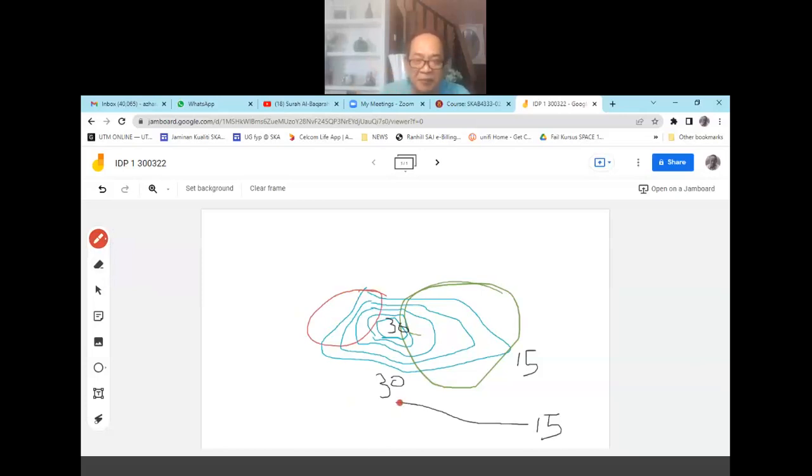are closely spaced together, it indicates that it is quite a steep slope on the left hand side. On the right hand side is a gentle slope, whereas on the left hand side indicates a sharp and steep slope. This can be observed by looking at the contour lines. If the contour lines are closely spaced between each line, then it indicates a very steep condition.